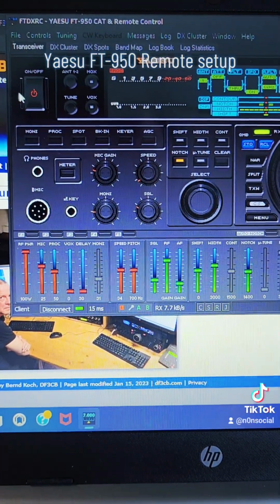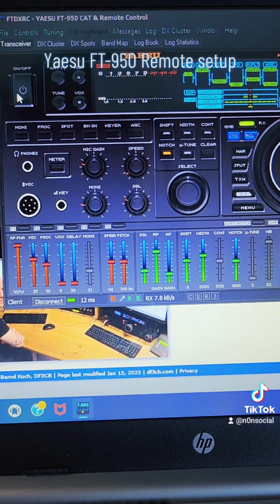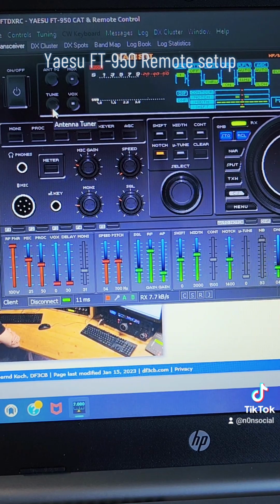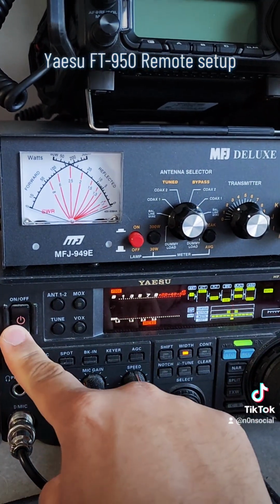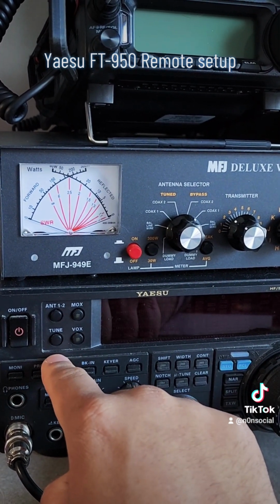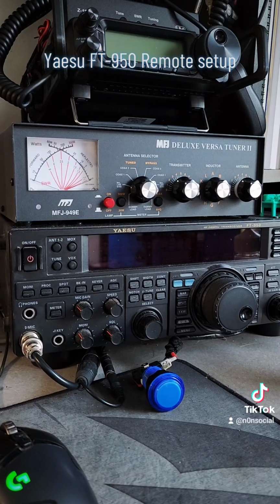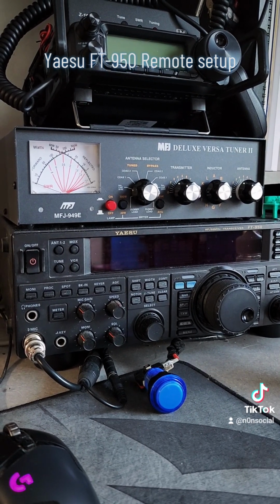So with this, I can come over here and, like I said, control every aspect of the radio. I can turn it off, I can turn it back on, I can tune the antenna. Now, I have to put the tuner into bypass mode and use the onboard antenna tuner on this radio. So yeah, that's how I set up my HF remote. Now I'm able to control it from anywhere that I have internet.